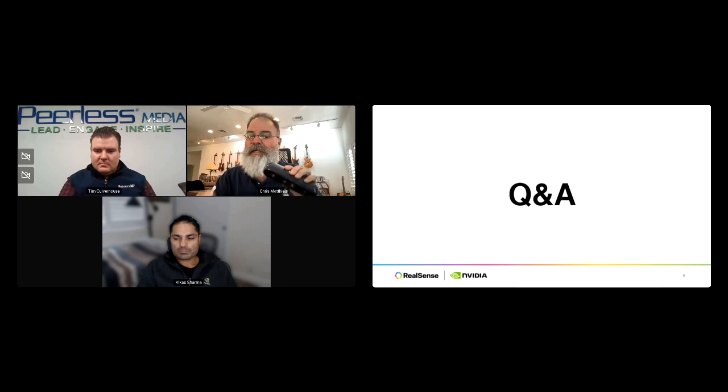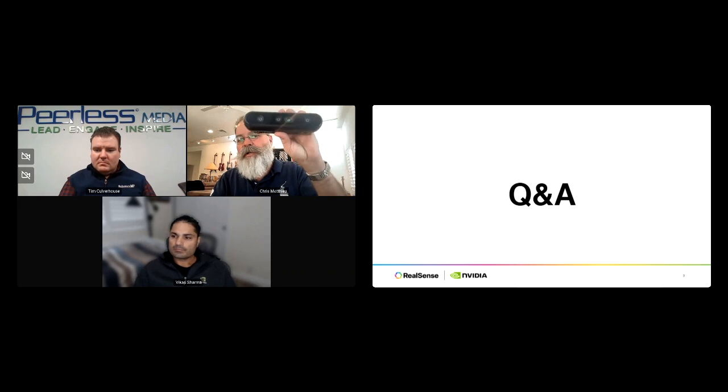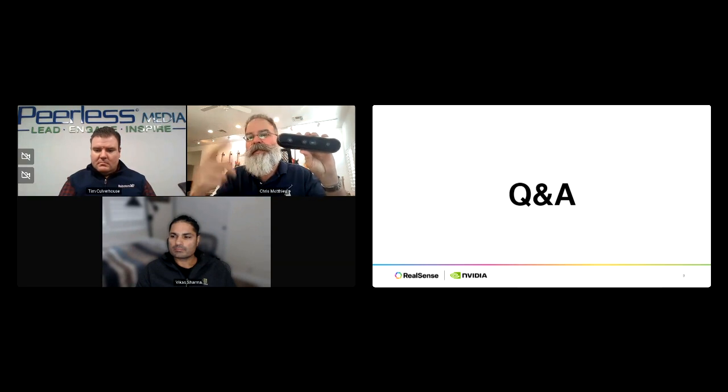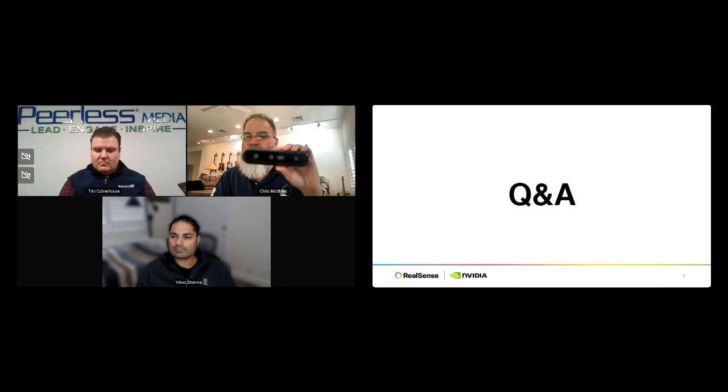I saw that question in the comments: the D555 camera is using DDS, so it's not a particular ROS flavor. It's using the messaging subsystem of ROS 2 in general. So whether you're on Humble or Jazzy or a newer version of ROS 2, you'll still be able to listen to all of the ROS 2 DDS topics streaming from the D555 RealSense camera.